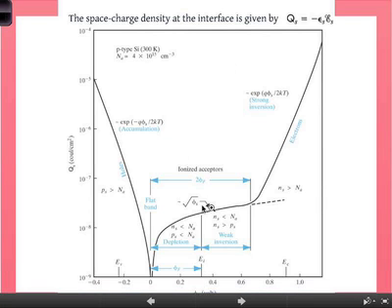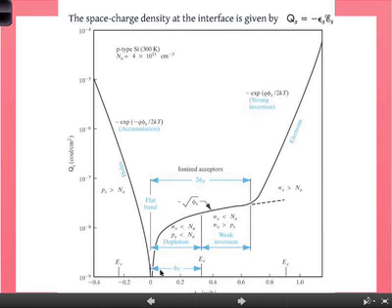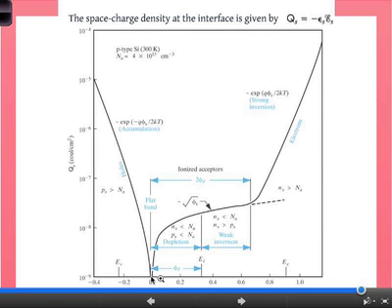So now you can plot for different situations. Phi s, the interface voltage, is the horizontal axis, and the vertical axis is this surface charge density. Okay? Now, let's start at 0. When you have 0 volts applied, so phi s is somehow related to the applied voltage. We'll relate that soon. But let's just see how the dependence works. So when 0 volts is applied, what do you expect the charges to be? It should be 0, right? There are no induced charges, nothing happens. So the charge density is essentially 0. It goes to 0. There's a singularity there in the equation.